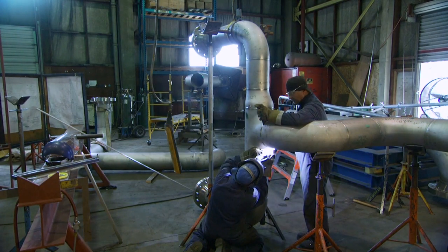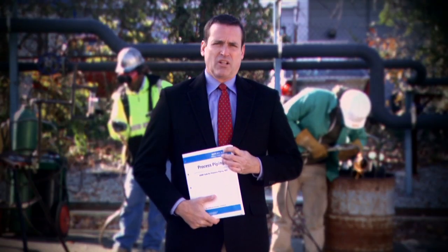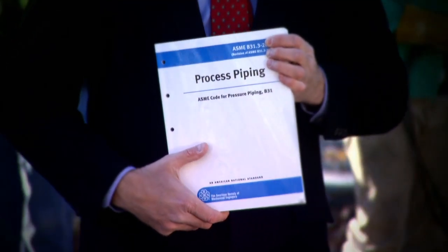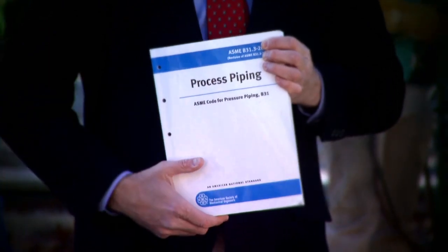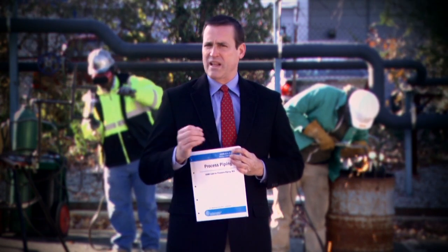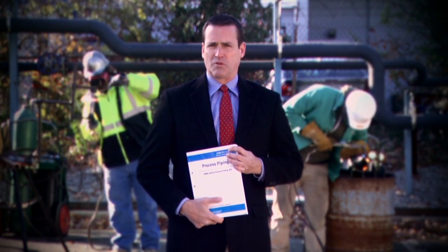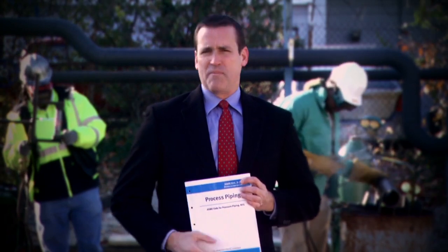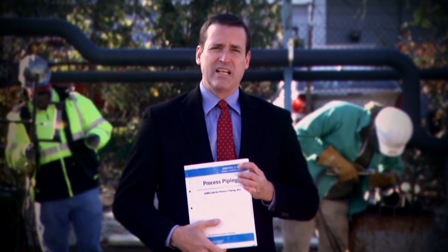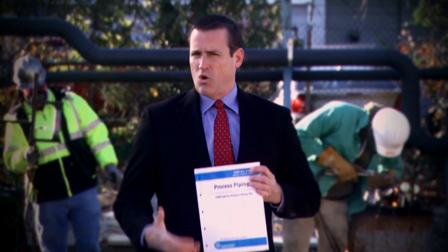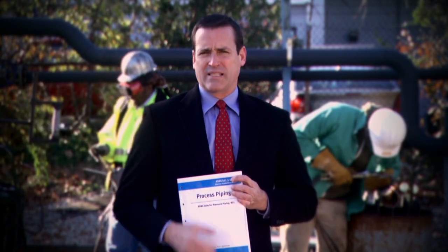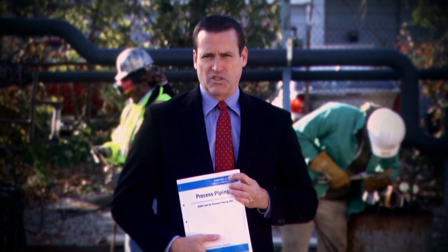lowest possible long-term cost. The American Society of Mechanical Engineers, or the ASME, first published the B31 American Standard Code for Pressure Piping in 1935. Today, this code consists of several sections and is recognized as standard industry practice when it comes to piping. As such, it provides the engineer with both a technical and a legal foundation for the design and installation of piping systems. Accordingly, the first step in the design of a piping system is to select the appropriate ASME B31 code section for the service conditions.